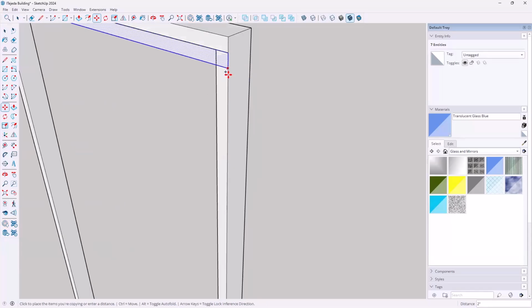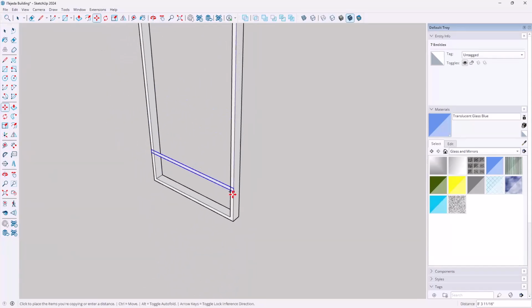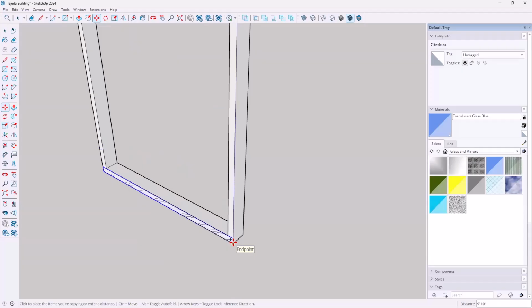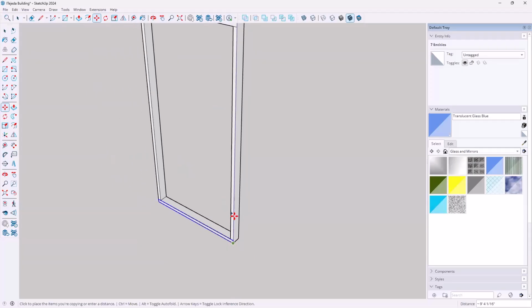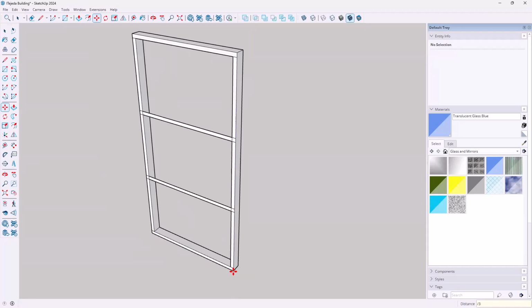Tap the control key. And I'd like to move it down so that it ends up right here on this endpoint. So let me just put the whole window in place. There we go. I want it to snap right there. And I click it. And then immediately /, which means divide, by 3. Enter. And excuse me, I have my 3 equal divisions.